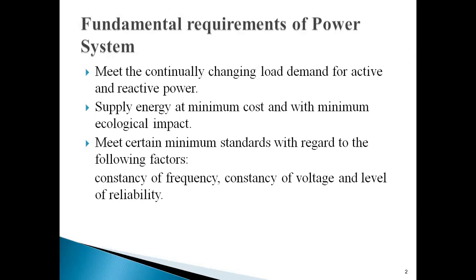When I say optimal, it should be fuel cost, and for that we have economic dispatch. We simulate it and try to find out, for the available load, what will be the minimum fuel cost. That will be decided, so that at minimum cost, or optimum cost, we are able to operate. Nowadays we speak about optimum with the help of evolutionary algorithms. The optimal is the best solution, also with minimum ecological effect.